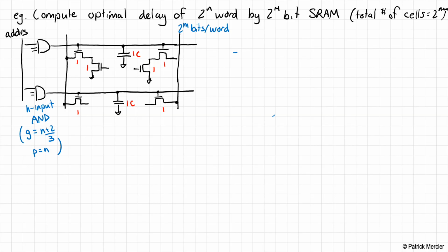So first of all, we can say that there's 3C per word line cell. What I mean by that is for any word line that connects to a cell, there's 2C of capacitance by connecting to those access transistors, and an additional 1C of capacitance just from the wiring itself. The logical effort of an SRAM cell is equal to 2.